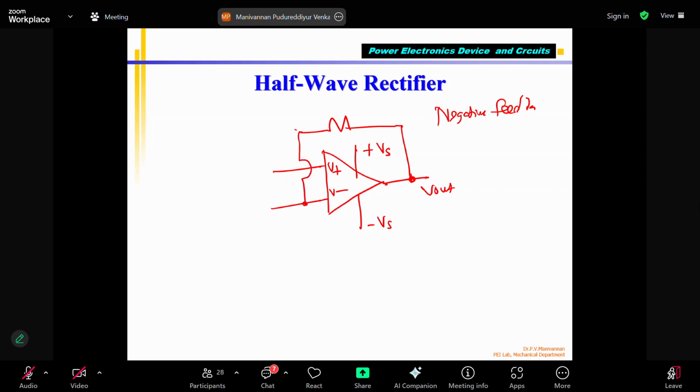Okay. Then this is my thermocouple, plus and minus. This is my TC. And this one also gives ground. Which one should go to ground? The negative, same negative, sir. The same negative should go to ground through one resistor. Yes, sir. So what is the resistor? This is called the feedback resistor. This is called the input resistance, R in.